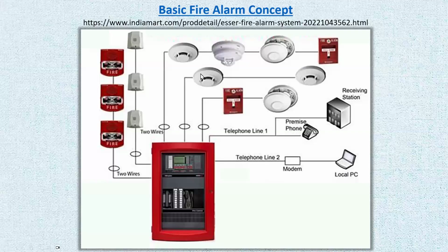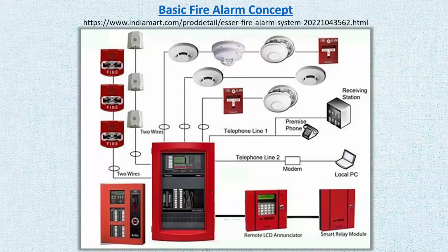All right. Now, when it comes to inspecting fire extinguishers, there's one crucial thing. The fire extinguisher should be taken out. It should be physically removed from that hanger or a cavity in the wall, and should be inspected for certain physical damage. Is the hose okay? Is the valve okay? Is the pressure good? Is there any physical damage, dents, rust signs, or whatnot? The general, just a visual inspection.